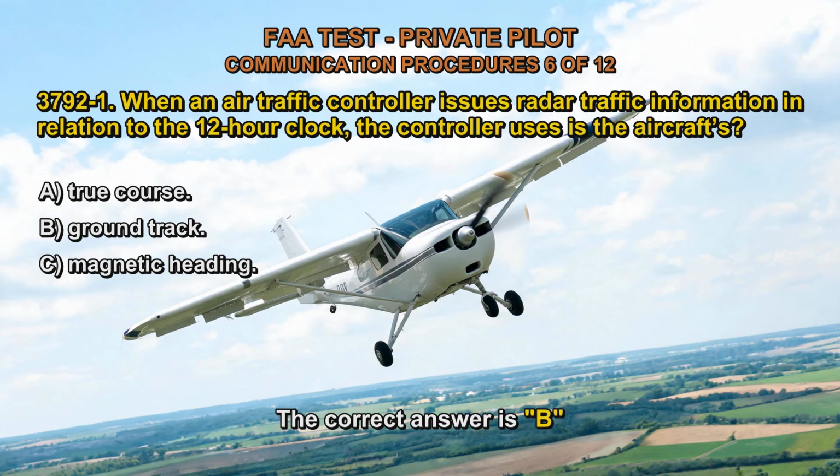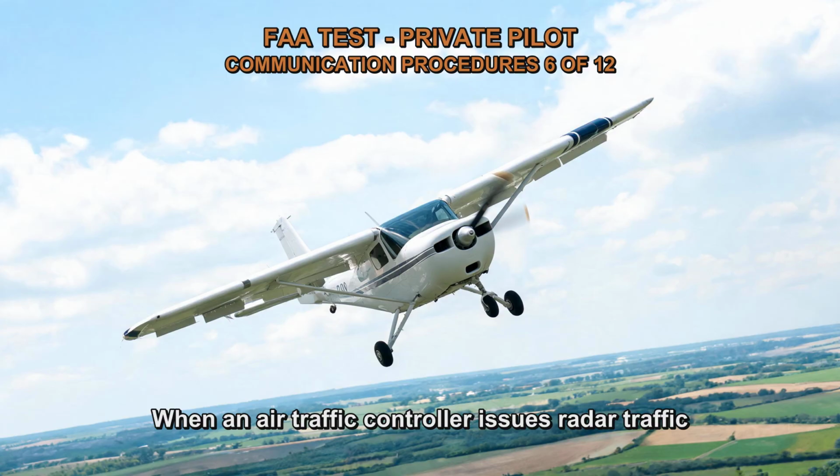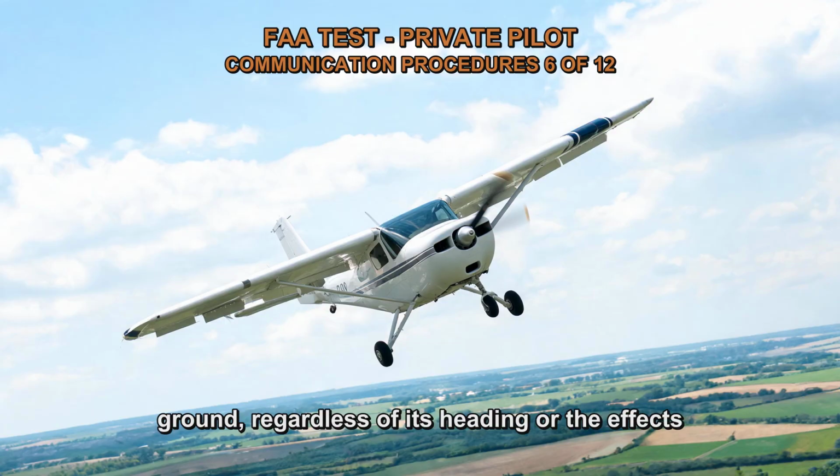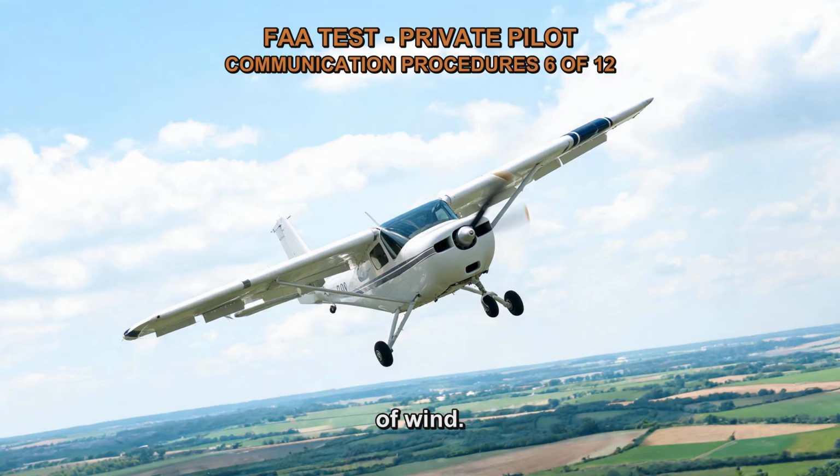The correct answer is B. When an air traffic controller issues radar traffic information in relation to the 12-hour clock, they use the aircraft's ground track. The ground track refers to the direction in which the aircraft is actually moving over the ground, regardless of its heading or the effects of wind.